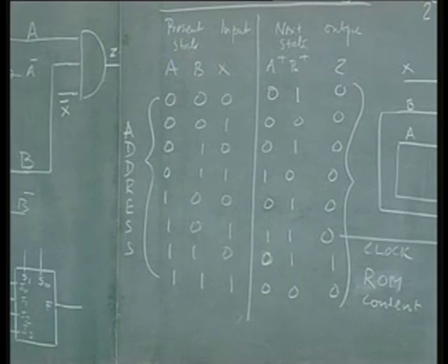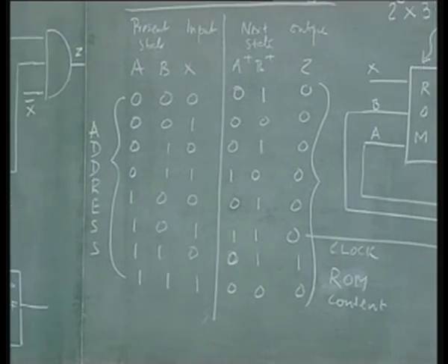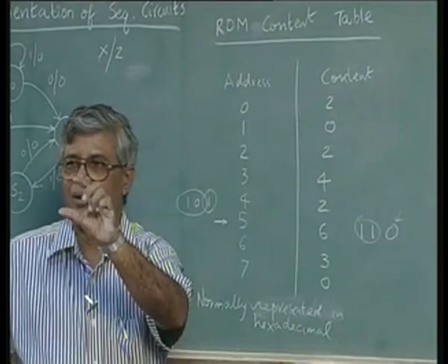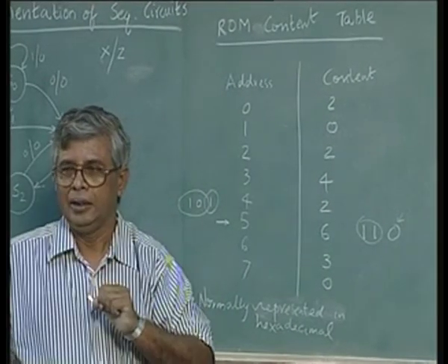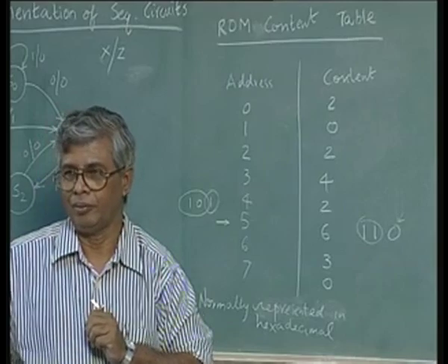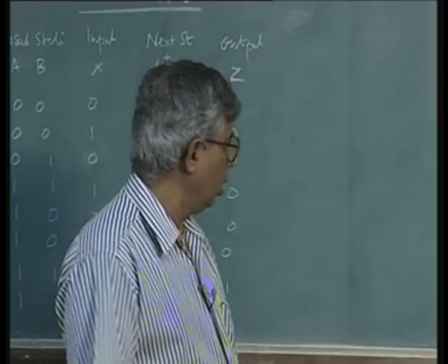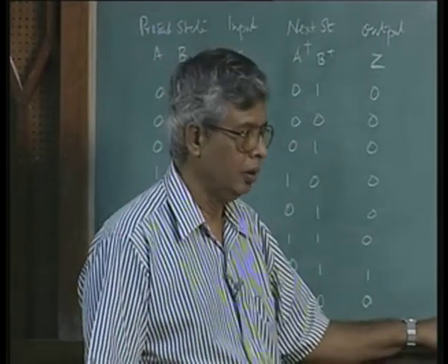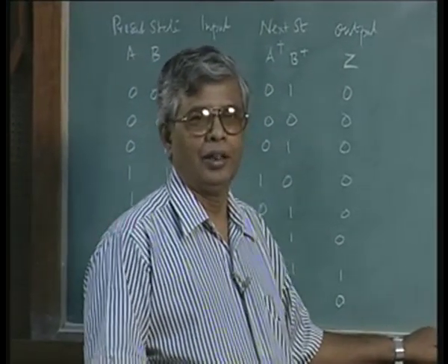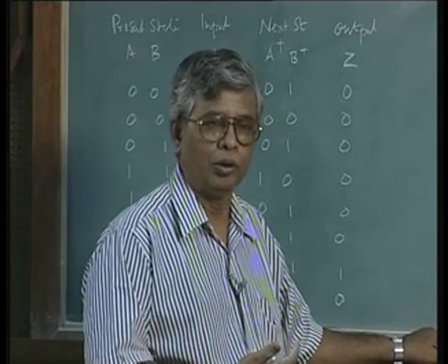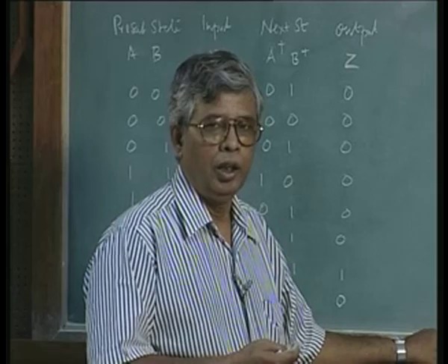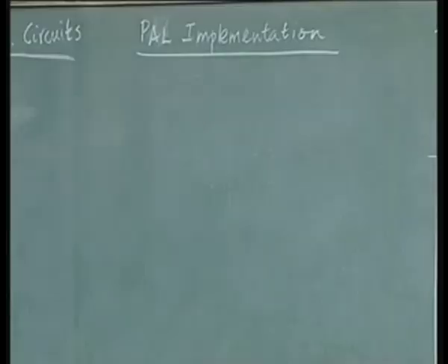A ROM of the correct size followed by 2 registers, I mean 2 flip flops, which can be given as a single IC. So now I have reduced further. In the next level of simplification, that means integrating the hardware, I am reducing the hardware count from gates to multiplexer to ROM. Even in the ROM design we had a ROM and a register, which is 2 flip flops.